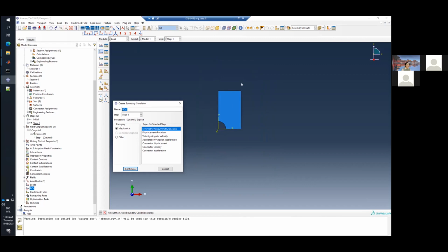And the third one is finally how we add the loading to this model. The third boundary condition we need to add to the top of this model will be a tension. And to simplify, to make this question simple, we only need a displacement controlled boundary condition. So we will not add load, we will only add displacement to control the global strain that we want. So we will add a displacement deformation at the top line as a third boundary condition.